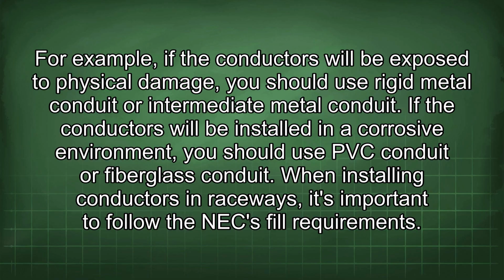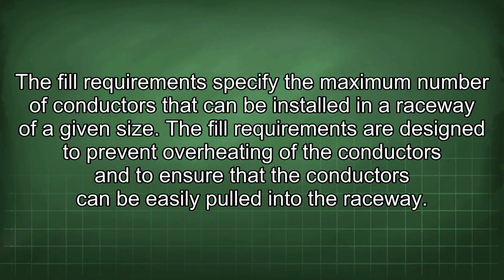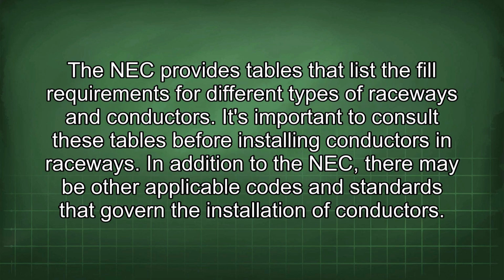When installing conductors in raceways, it's important to follow the NEC fill requirements. The fill requirements specify the maximum number of conductors that can be installed in a raceway of a given size. The fill requirements are designed to prevent overheating of the conductors and to ensure that the conductors can be easily pulled into the raceway. The NEC provides tables that list the fill requirements for different types of raceways and conductors. It's important to consult these tables before installing conductors in raceways.